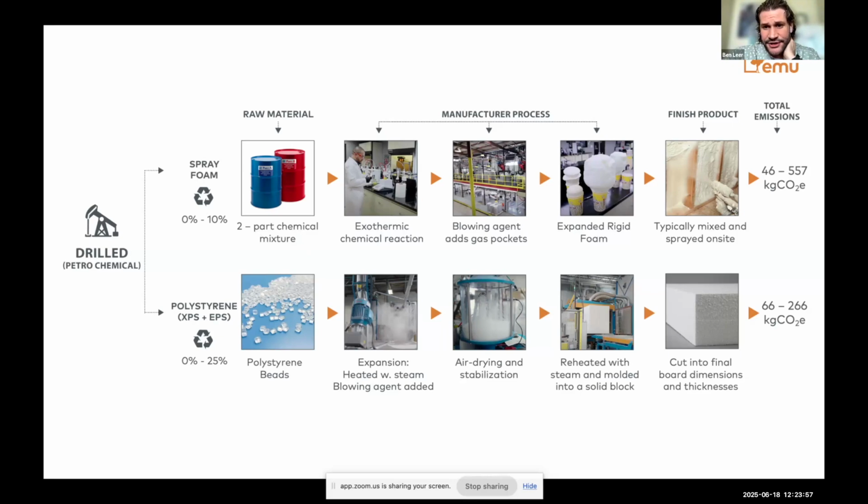So you get this expanded rigid foam here. You can kind of see this coming out of the popcorn. You mix the two agents and it expanded. We usually do this process on an actual construction site. So this is the on-site spray foam that you see being applied here. The two things are mixed together. You blow it into your cavity, into your roof assembly, and it'll expand and create this rigid foam.